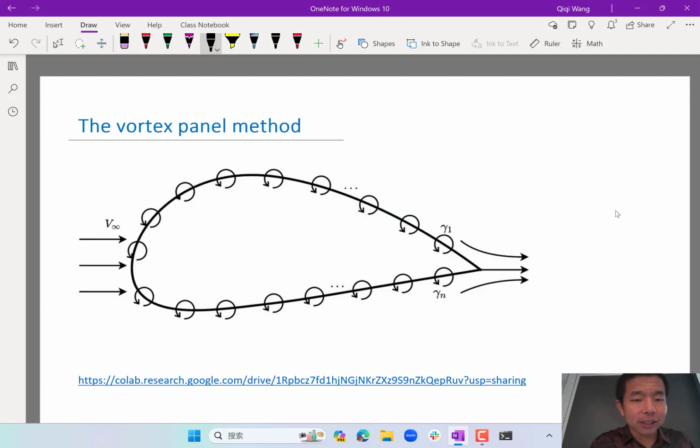Okay, so today we are going to continue to work on vortices. In the last lecture, we started thinking about the superposition of a uniform flow field with a vortex or a number of vortices. Today we are going to exercise that and figure out how to construct a collection of vortices that, when we add all of these vortex flows to a free stream, gives the flow around an airfoil exactly. After that, we compute the pressure on that flow field to figure out what forces the airfoil would get.